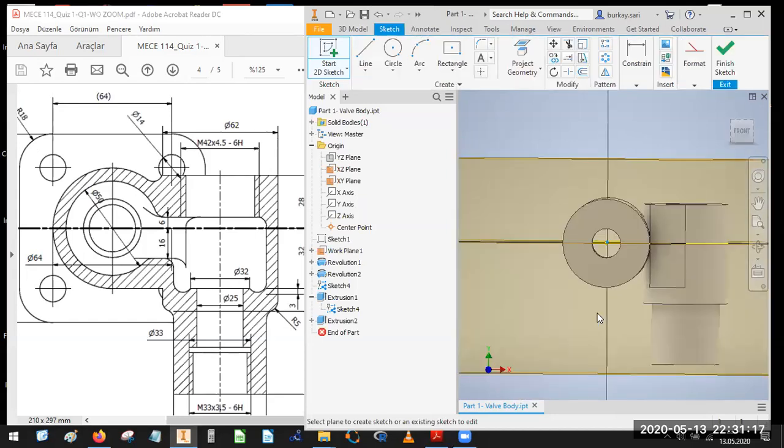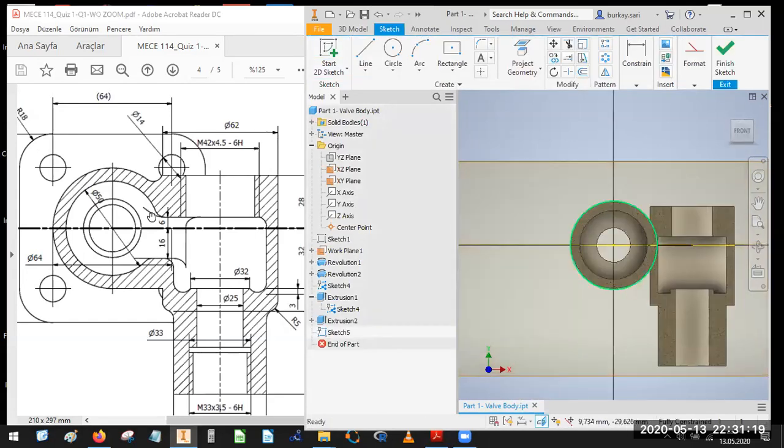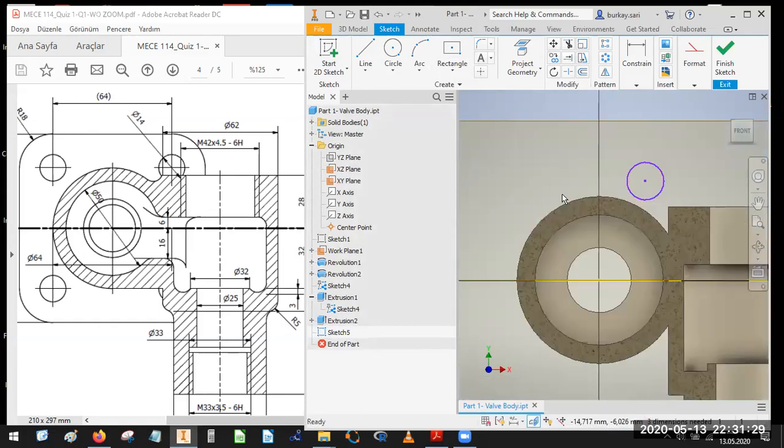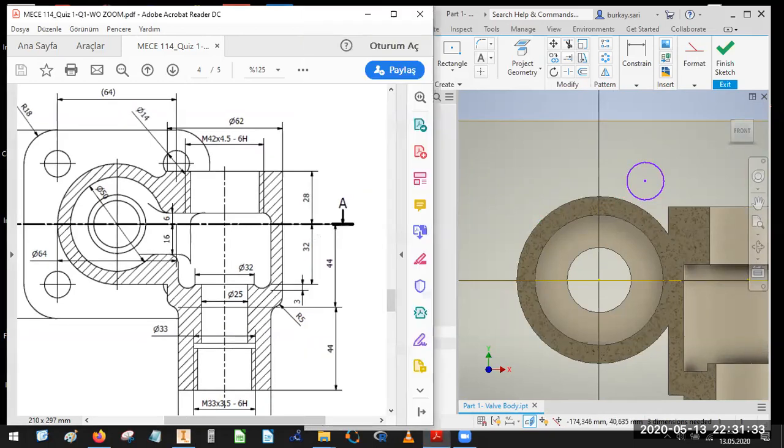With F7 tool, I would like to just combine these 2 items. Here, what I'm going to do is I will use a tool circle here, and I would like to have a fillet tool, which can be the 5 millimeter in radius.